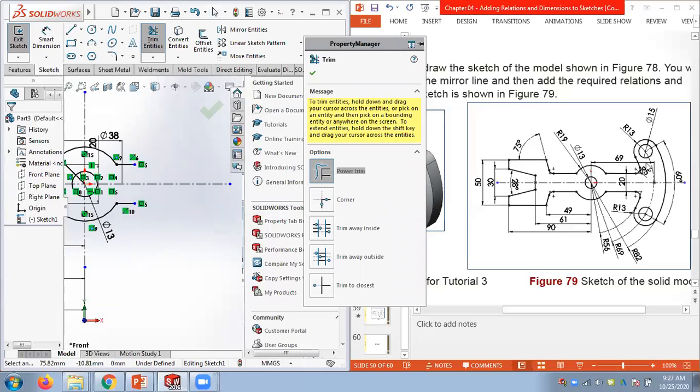Then we can move on to the other area. This one, if I try to use the arcs, we can draw an arc here, another arc here, and draw these small arcs and get it from the arc tool. But it takes some time to use the arcs. So there's a tool called slot tool in SolidWorks. We have four shapes basically. First one is a straight slot. I will quickly go through these things before I come to the tutorial. So I will save this file.